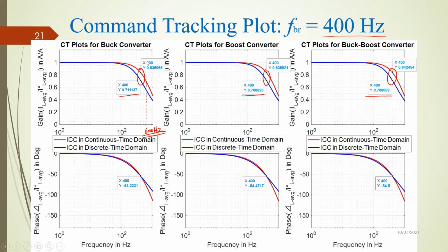In discrete time domain, you are already taking care of the switching behavior of the converter, and the additional delays from computing the mean values are also eliminated. There is a third advantage: you just need to sample the signals at the two extremes, so you don't have to do many samplings.